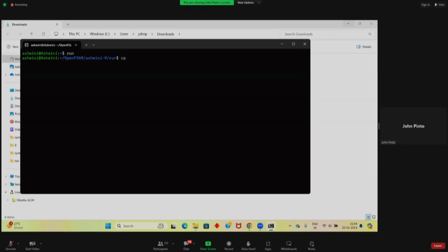We have shared a list of commands with you yesterday, so you should be able to understand now. cp -r means I'm trying to copy a folder from my home, the tutorials, and inside foam tutorial, it is in the incompressible folder, and in the icoFoam folder, and inside that cavity, and inside that there is one more cavity folder.